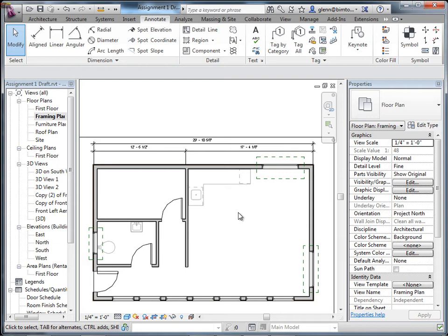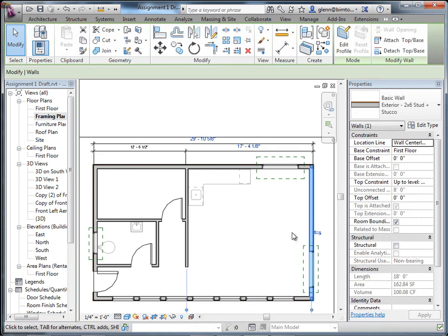Well, some people do, but never put out plans that have that degree of precision, unless you're doing fine steel work and you can actually control that. Most framers, if you get down to the 1/2 or 1/4 inch, you're doing really, really good. So what I might want to do with this building is, it says 29, 7, and 10 and 5/8. I'm going to go ahead and choose that outside wall and actually just change that to 30 feet. Because that's just probably a better dimension in the scheme of things.